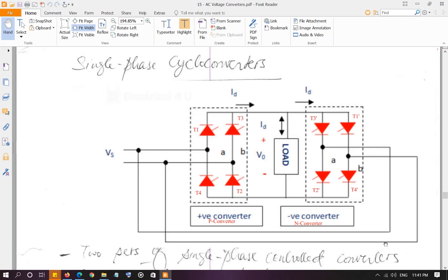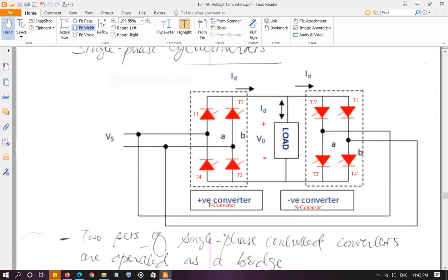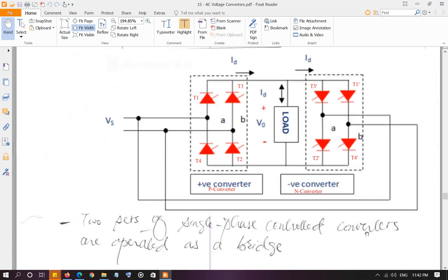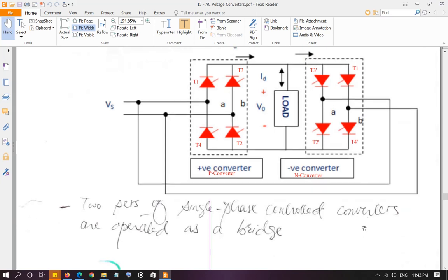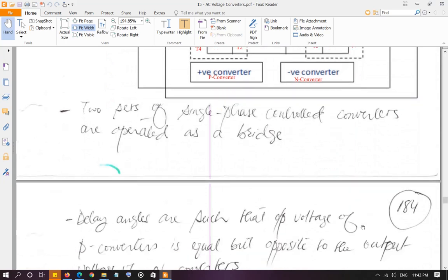So based on how much frequency you need at the output, let's say you need 1/2 of the input frequency. For one half of the input frequency, your time period is going to be double the time period of the input. So if your input time period is 1 millisecond, the output time period has to be 2 milliseconds, right? Okay, so let's look at how it is going to work.